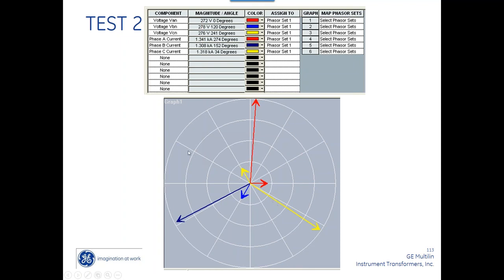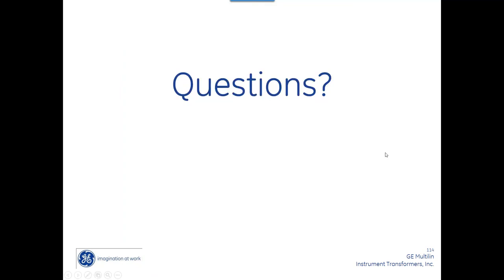If I saw this go in this direction, 180 degrees backwards, what's that tell me? My dot orientation's wrong. There turns out, guys, there's like 32 different combinations that I've come up with. So you've got to look at this phasor diagram to figure out what's the right answer. Trying to guess and swap A and B, because you may have A current with C voltage. I mean, it's a mess.